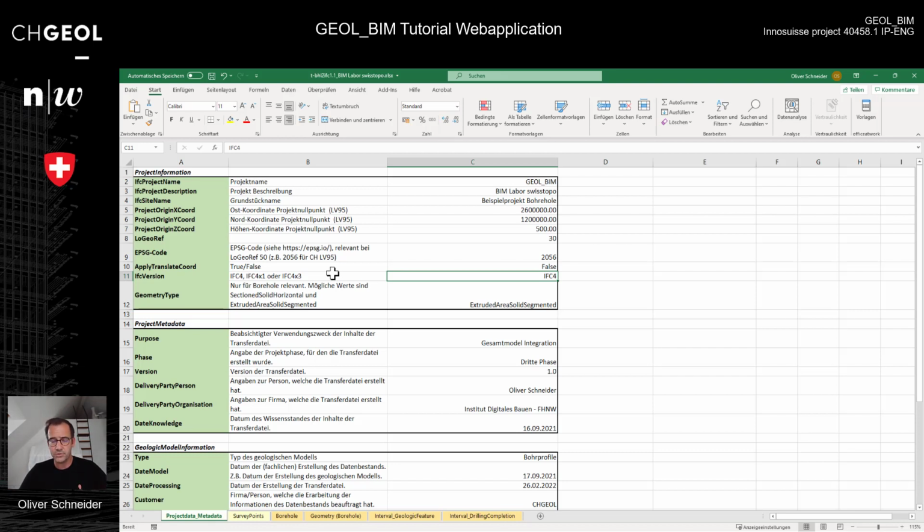That's especially important for some of the features on geotechnical stratum, which are available only since 4.3. And for that application, we have different mappings implemented to IFC4 or to IFC 4.3. So the mappings are also explained in the reports, so that you can also have an explanation.